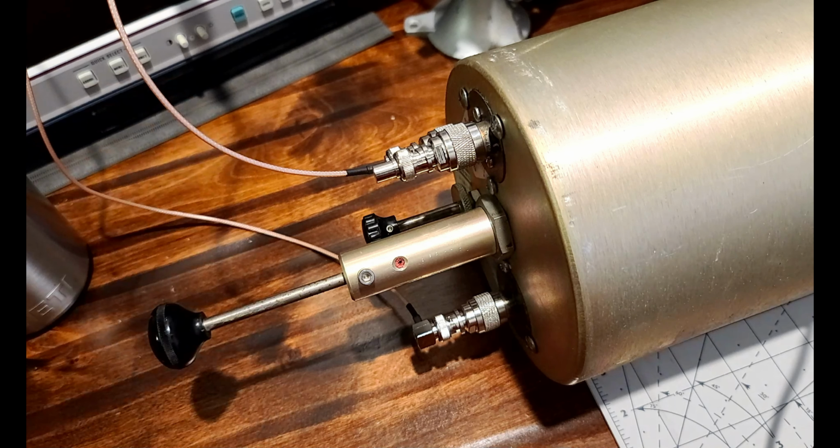But there's also another method for us to double assert that the cavity filter is in fact right on the nail at that desired frequency of 144.39, and that method is called the return loss of the cavity filter. So before we go to the return loss method, I want to quickly show you, just to refresh our memories, how the frequency response was from the previous transmission loss method we implemented in tuning this filter. So let me switch the visual to the spectrum analyzer, and let me show you exactly what we saw in our previous video as the output.